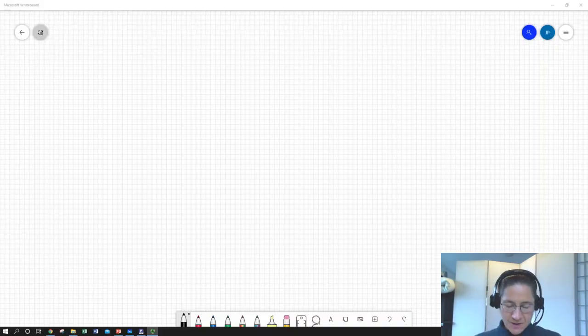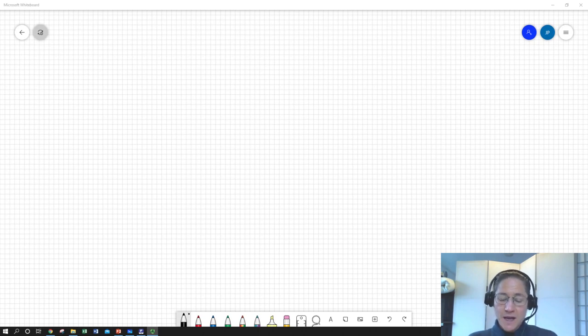Welcome, dynamics students. This mini lecture will include some demo problems on the subject of rigid body planar kinetics. So we will be examining the effect of forces and net moments on the acceleration of a rigid body center of mass when it's moving in planar motion. That means it's moving in one plane, and the vector direction of moments and of all of its rotational velocity and acceleration is normal to the plane.